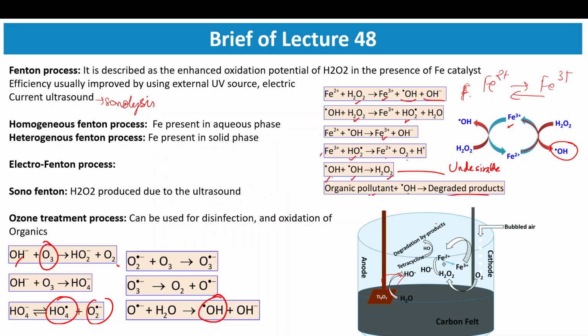disinfection of water. So these are the reactions that usually take place when ozone is present in water for the ozone treatment. And basically, when you are using ozone, you are trying to generate hydroxyl radical. Since ozone has three oxygen atoms and a resonating structure, it immediately reacts to form, through these reactions, hydroxyl radical.